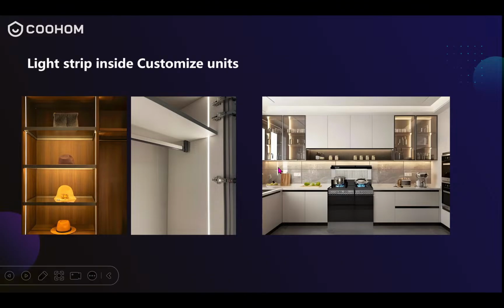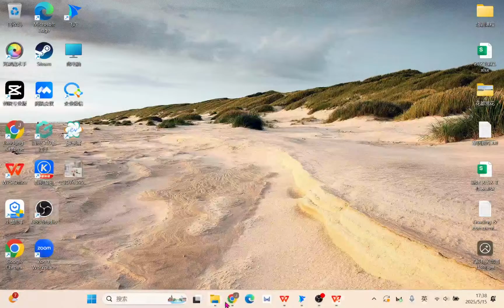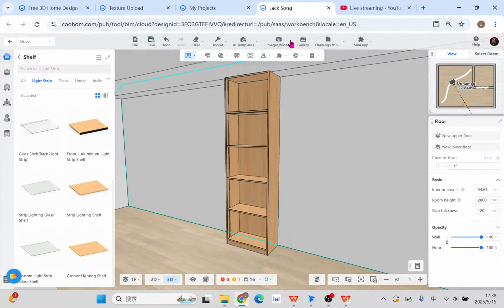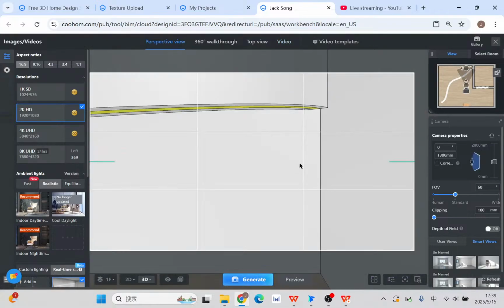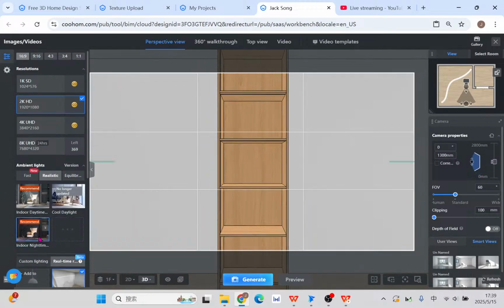Everything's finished. And finally, for all these lights, what you need to do is just put one rectangle with 50, 50 thickness, okay, and 1200 brightness, and it's fine. Just remember that. It's almost a universal law to do the render. Yeah, let me show you adding another.